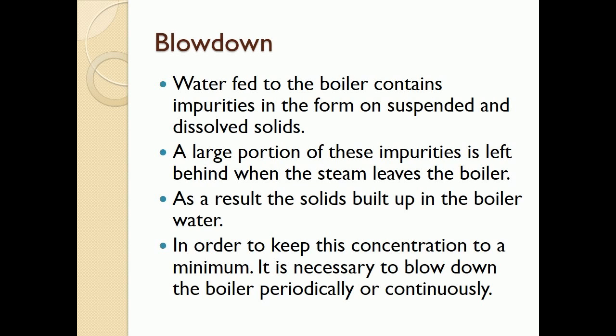What is boiler blowdown and why is it important? Water fed to the boiler contains impurities in the form of suspended and dissolved solids. A large portion of these impurities is left behind when the steam leaves the boiler. As a result, the solids build up in the boiler water. In order to keep this concentration to a minimum, it is necessary to blow down the boiler periodically or continuously.